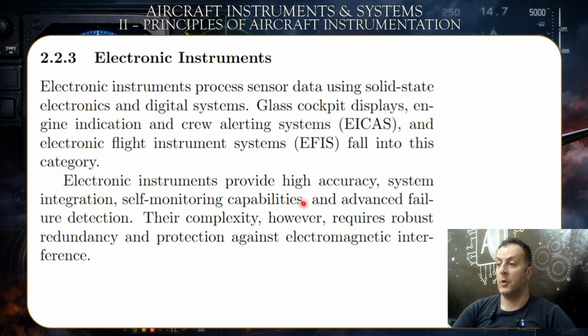Another example is an engine going down or high oil pressure. Electronic systems can self-monitor all of these indications, so whenever a value is beyond nominal and dangerous, they display an alert or trigger a sound alarm, a buzz, so that you pay attention that something is not going right and can troubleshoot the problem immediately.